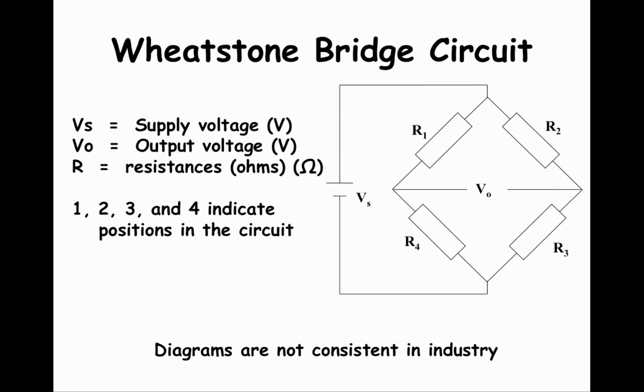Here is a sketch that shows a Wheatstone bridge circuit. Let me explain the elements of the circuit. The four rectangular boxes represent four resistors. They are numbered 1 through 4, going clockwise and starting in the upper left side. So the circuit has four resistors numbered 1, 2, 3, 4. In many cases, we will assume that resistor 2 is the one that changes if only one resistor changes. In that case, the other three resistors, 1, 3, and 4, are assumed to be constant.